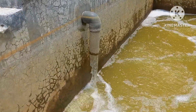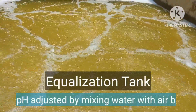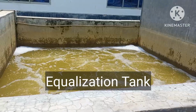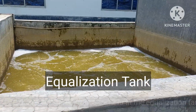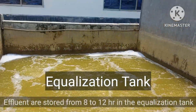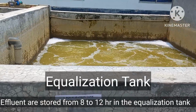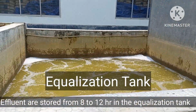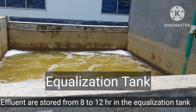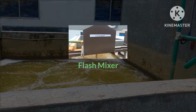The wastewater will be pH adjusted with static mixers and an online feeding mechanism and sprayed into the equalization tank, thus providing a cool down effect necessary for biological requirements. Sufficient retention time of 24 hours is provided to equalize and homogenize the variations in the flow and pollutant concentration, with aeration in the equalization tank.